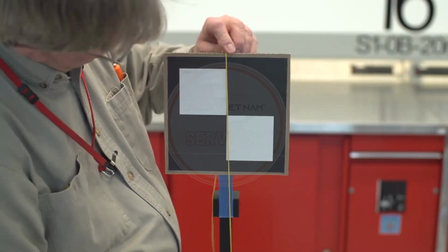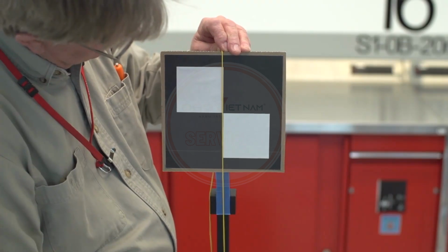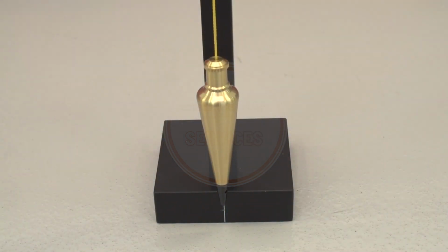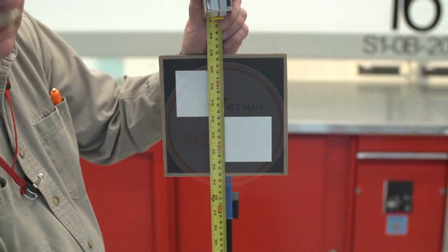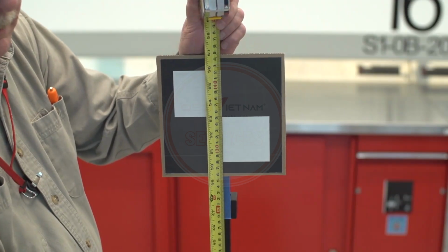Install the reflector to the stand and use a plumb line to make sure that the center line of the target aligns with the center line on the base of the target. Set the height from the center of the target to the ground at the specified number, in this case 1,350